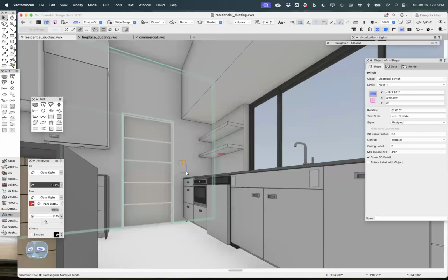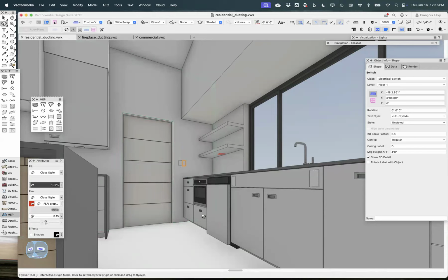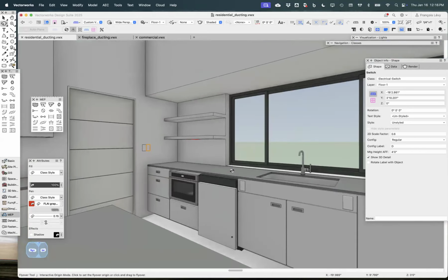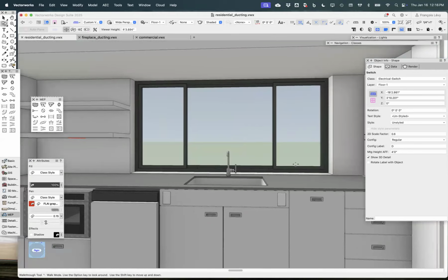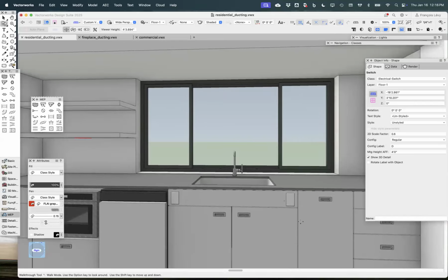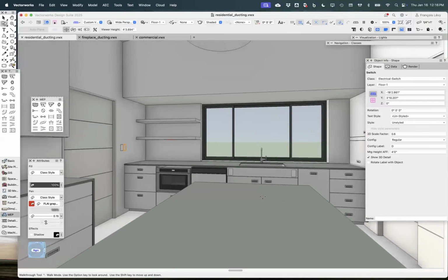I know that's very prosaic, but the residential code is such that when you do a kitchen design like this, where you've got this big expanse of glass, and lots of really great tile and finishes, the last thing you want to do with a backsplash like this is to stick a couple of outlets in there.